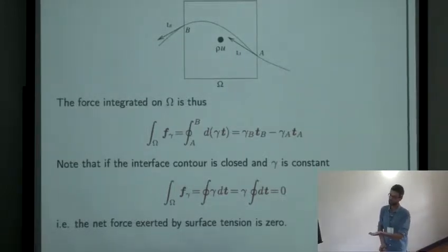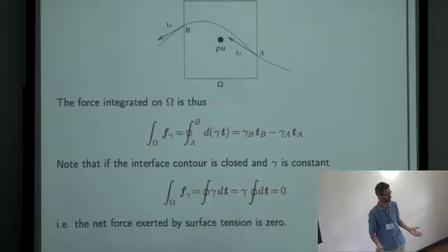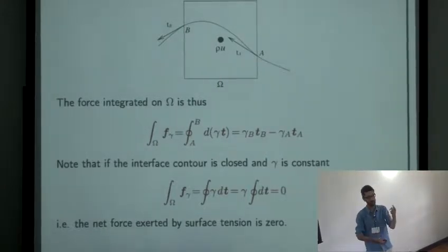So an important property of this type of construct, you see right away, is that if you integrate the surface tension force along a closed curve, you get zero contribution, right? That's what I'm talking about when I say momentum conserving. The contribution of these forces should be zero. Otherwise, each of your little drops has a little engine, which makes its center of mass move just due to surface tension, right? That's bad. Clearly, that's bad.